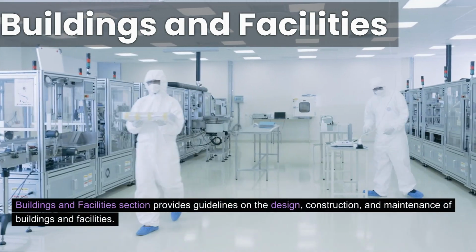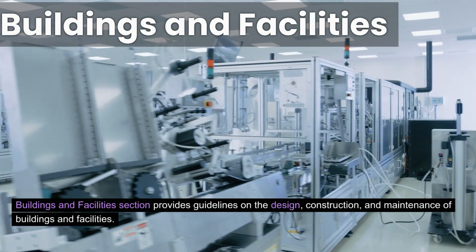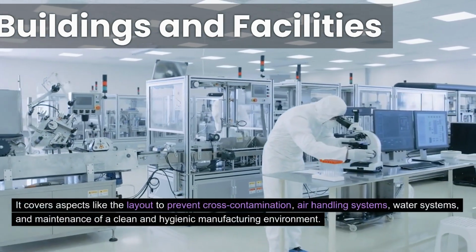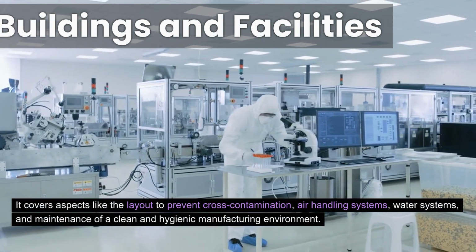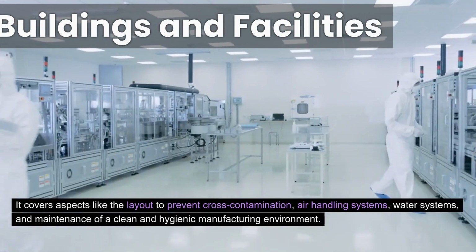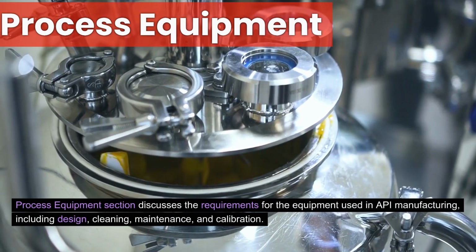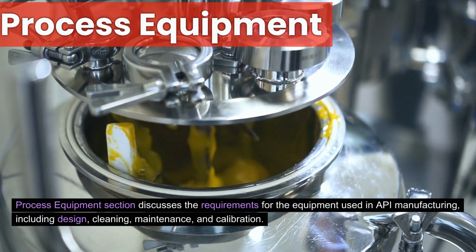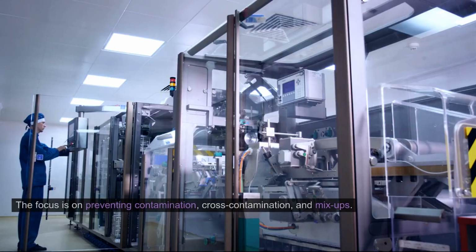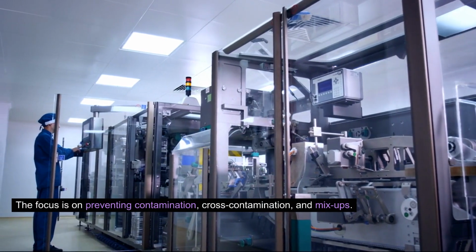Buildings and Facilities section provides guidelines on the design, construction, and maintenance of buildings and facilities. It covers aspects like the layout to prevent cross-contamination, air handling systems, water systems, and maintenance of a clean and hygienic manufacturing environment. Process Equipment section discusses the requirements for the equipment used in API manufacturing, including design, cleaning, maintenance, and calibration. The focus is on preventing contamination, cross-contamination, and mix-ups.